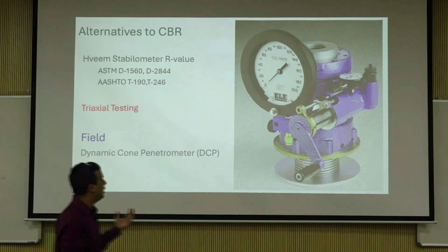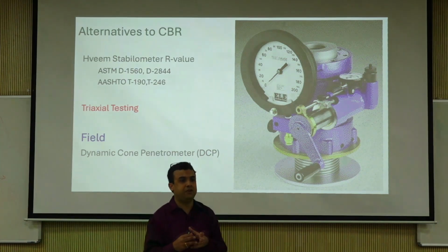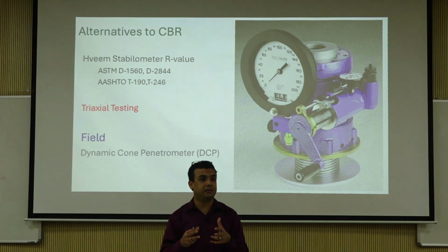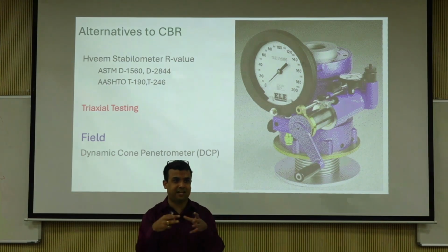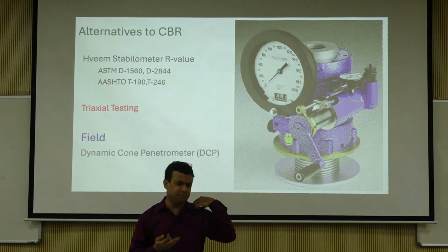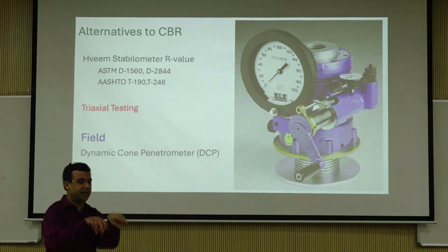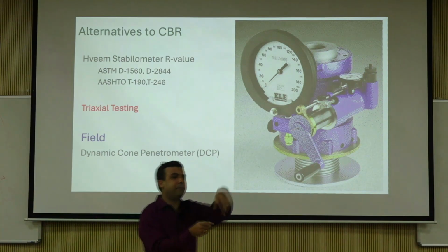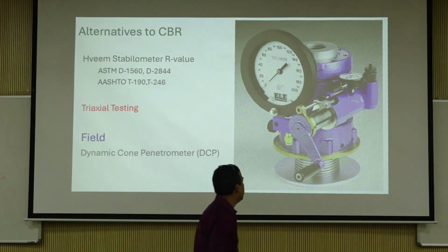The whole idea is related to Poisson's effect. What is Poisson's effect? Say again? That's Poisson's ratio, minus epsilon 3 over epsilon 1. That's Poisson's ratio. What's Poisson's effect? Yeah, exactly, something like that, right? I would not say x and y because I can always put x and y in the same direction, same plane. But yes, longitudinal axial compression will lead to radial expansion.